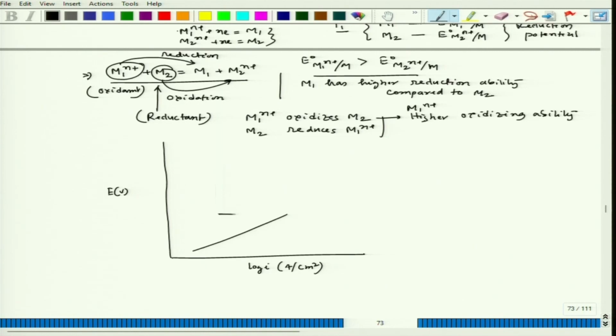So, this is my active metal. Now, as per the previous understanding, we are not writing all those details. This is the active-passive metal anodic part, or anodic polarization part, and we see a passive zone, which is this one. This one is basically the active zone. Passive, and then this is transpassive.